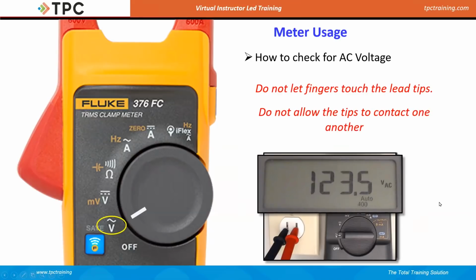It is safer, yeah. And it's really easy, especially troubleshooting on terminal strips, to have these touch each other, right? You have two leads down on two terminals and they touch each other. Again, a lot less likely to happen if you put on your caps.